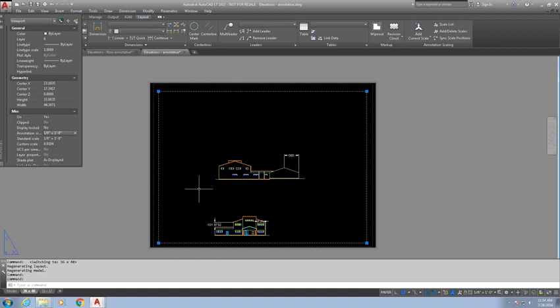And that's the goal here, to add flexibility, because maybe you don't always know what scale you're going to need for your viewports, or maybe your model is too big and maybe you do need to try out different scales to fit on the piece of paper. And that's where annotation scaling comes in really, really nicely because you can maintain it all with one annotation scale, or one dimension style rather, that's annotative. And there are a couple of variables that control things.